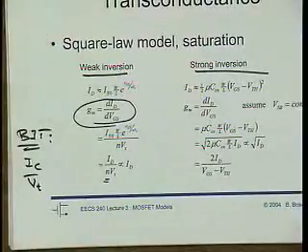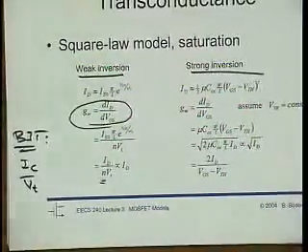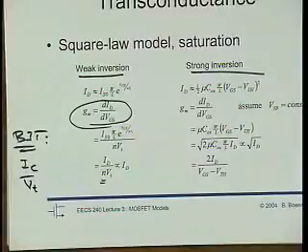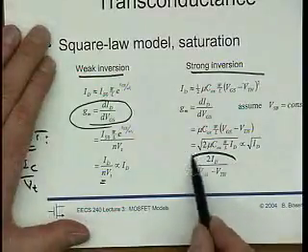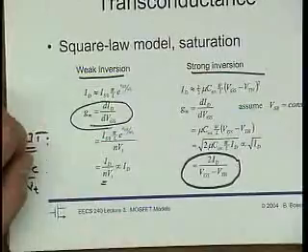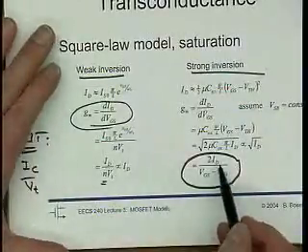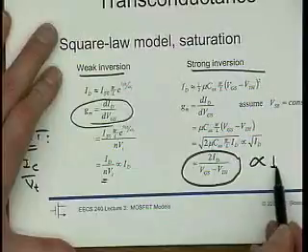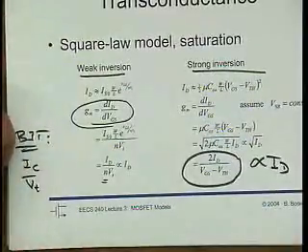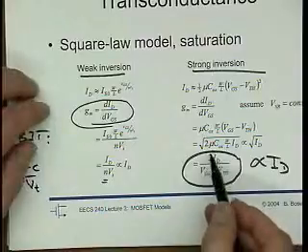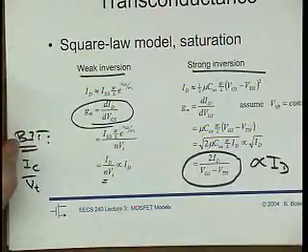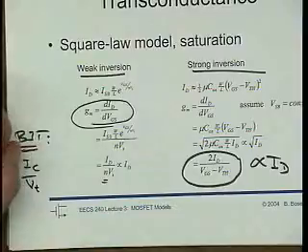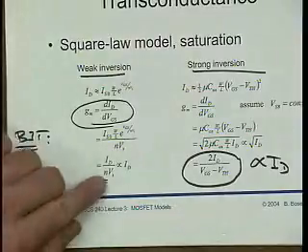So the transconductance is really proportional to the amount of current that I stick into my device, and then it's also cut down by Vt. Okay. Now, if I go to strong inversion, I assume for a moment that we had this square law model. Then I get this expression here. Incidentally, it looks very, very similar to the bipolar device or to weak inversion. Again, we are proportional to ID. But the proportionality constant isn't so good anymore. Well, the factor of 2, of course, is nice. Wonderful. But VGS minus VTH usually is a lot larger than VT.